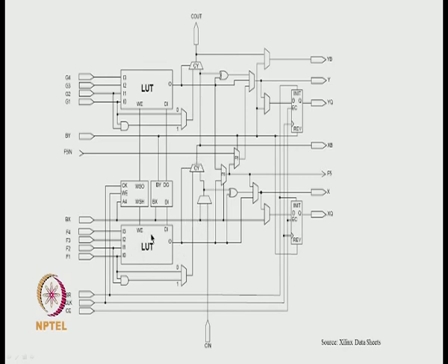It works along with the A exclusive-OR BI here, and it goes there and forms the carry logic for the next I+1 index, and this is the sum. So the sum is formed using this lookup table and the XOR gate. In the I+1 stage there is this lookup table and the XOR gate, and the carry circuit is here for the ith stage, the I+1 stage is this, and so on.